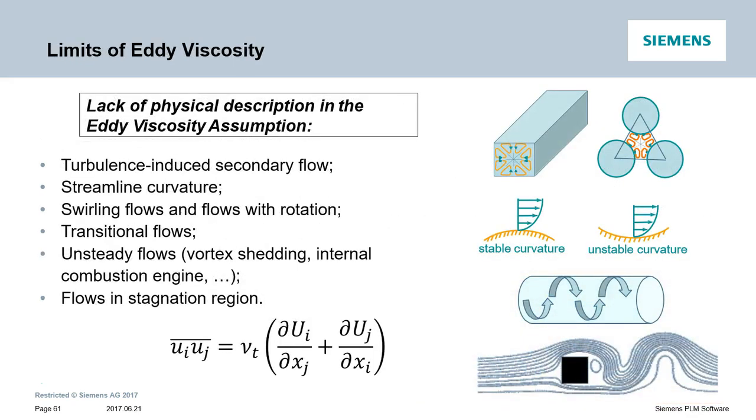Okay, so going through these different linear eddy viscosity models, we have learned that there are some inherent limitations to these models. Maybe this stress-strain relationship is not as simple as assumed by Boussinesq. So as a result, these linear eddy viscosity models are unable to capture the turbulent stress anisotropy, secondary flows, curvature effects, etc. For example, the fully developed flow through ducts with non-circular cross-section.